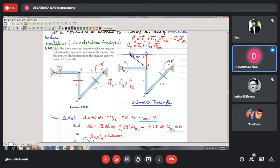See here, omega AB is equal to omega. Now you see, this is the relative velocity expression, correct? So mentally place this vector here. Suppose it represents r times omega AB. This is r into omega AB. Now you assume that if this point is kept fixed, how will this tangential velocity be realized? It can be realized only when this link's angular velocity is in this direction. So I find that the angular velocity of the link AB has the clockwise sense. That means the arrow must be in this direction.